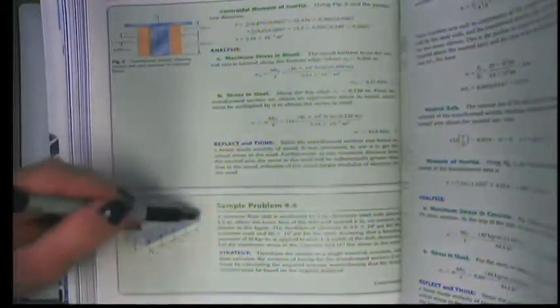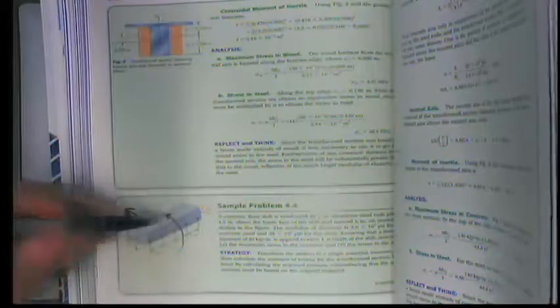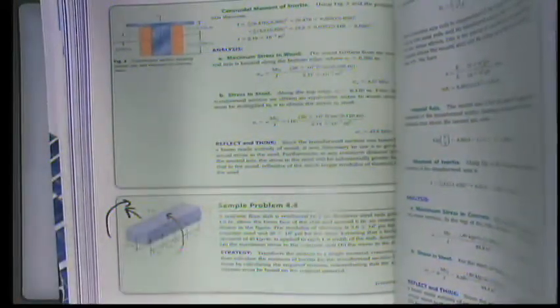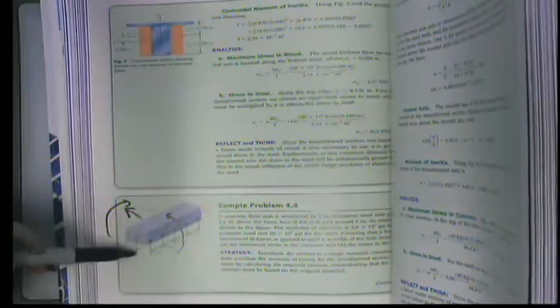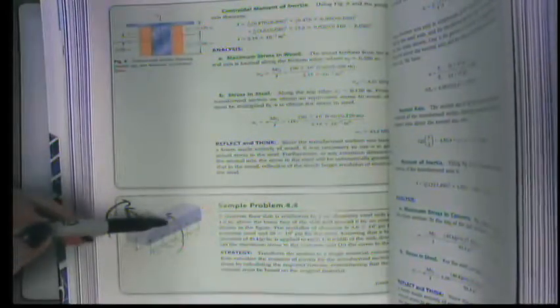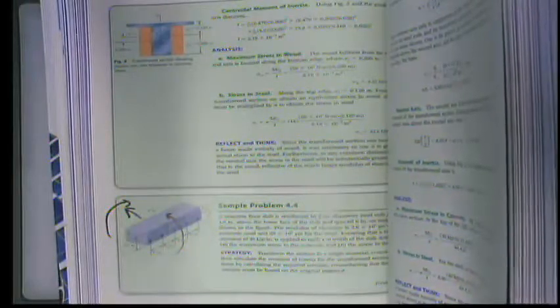We're just looking at a piece of it, and it's being loaded on top, and so the moment is bending it. I'm going to do something, since it's my book, is bending it like this. Okay? That's that little arrow diagram right there. So what we're being told then is that the entire slab is 5.5 inches in height. That distance from the top of the concrete slab to the center of each piece of rebar is 4 inches, which means basically that there's 1.5 inches below the center that's really also not doing us any good.